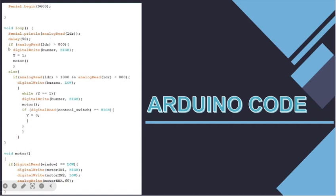But as we can see, if the value of the LDR resistance is below 800, the buzzer will be automatically high and the value of y will become 1, and this motor section will be activated. In the motor section, we have defined that if the digital read window equals low, then in1 will be high and in2 will be low, and the last line, analog write motor enable pin comma 60, depicts the speed of the motor.